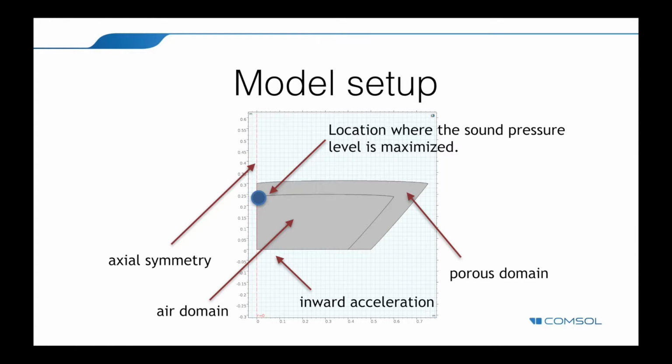The concept of best is expressed through a scalar metric in COMSOL called the objective function. Substantial care must be exercised when choosing the objective function, because solely these requirements will be satisfied by the final optimized solution. Different objective functions will result in different optimal geometries and/or solutions. COMSOL enables the inclusion of several independent optimization criteria in a single objective function.